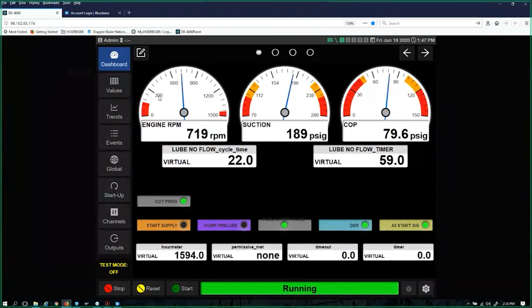The reason I do that is because if I set a 60-second prelube timer for the compressor, then I send a start signal to the engine, and the engine's controlling its own prelube and crank cycle, the compressor's continuing to prelube. And some manufacturers will say they want up to a 2-minute prelube time. Okay, let me get this straight. That 60 seconds you put in originally was for the compressor prelube, not the engine, right? Correct. I use an Arrow 3500 as our example today. Oh, okay. Now I got it. I was off base, sir.